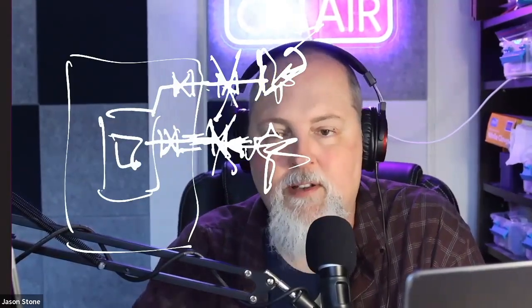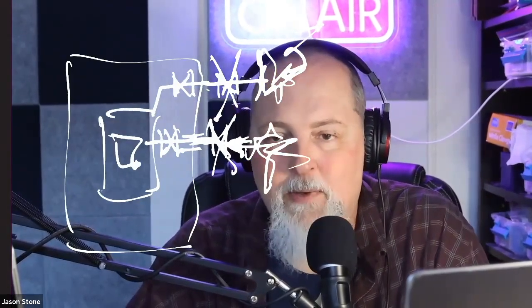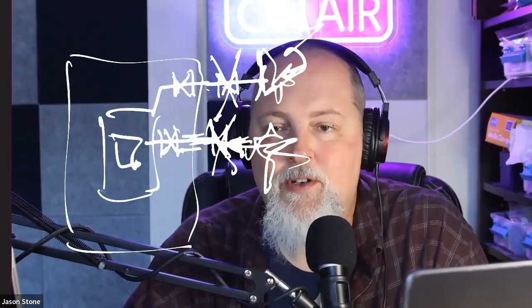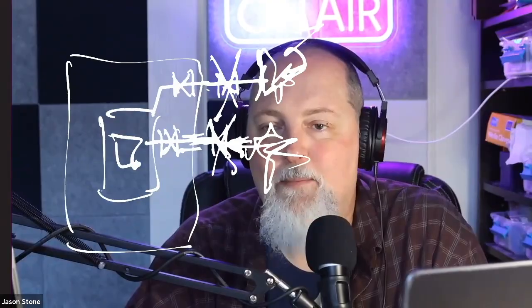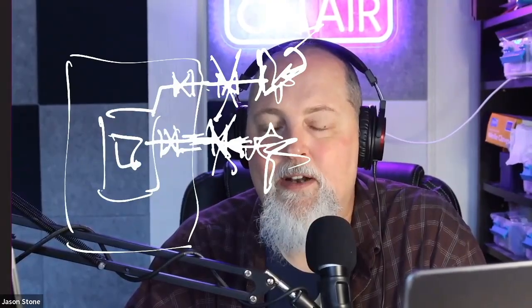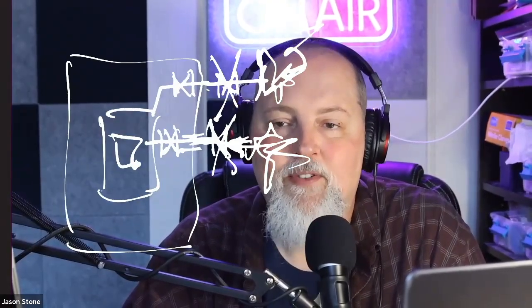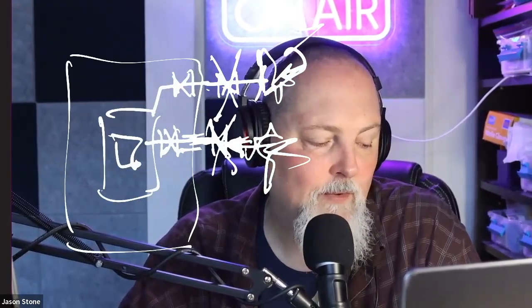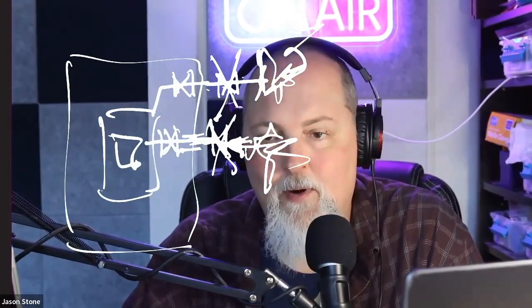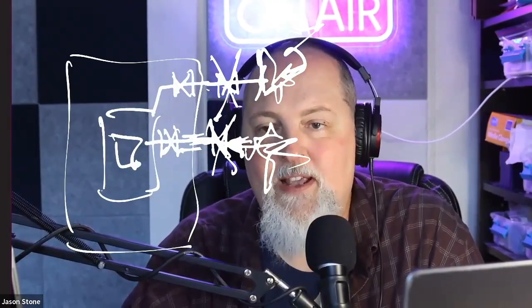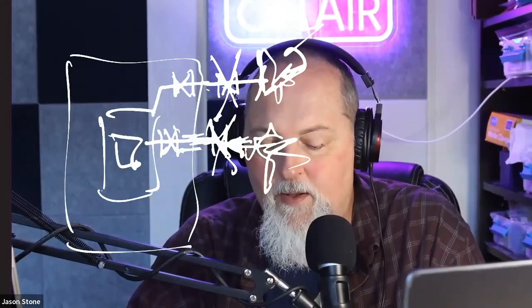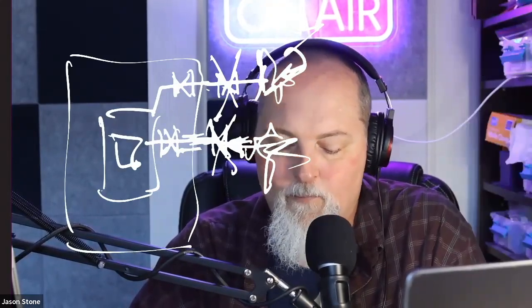There are lots and lots of containment isolations. We have sampling connections, ventilation. We have all these different pipes going in and out of primary and secondary containment, and they all have these isolations. An isolation is an automatic closure of the valves to isolate primary containment from the environment. This helps keep any of the bad stuff in the non-people space. We don't want it to get into the people space.